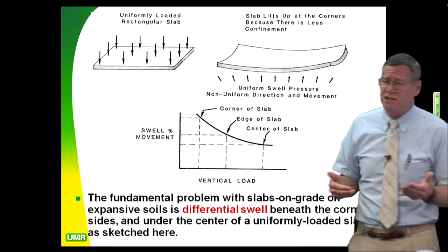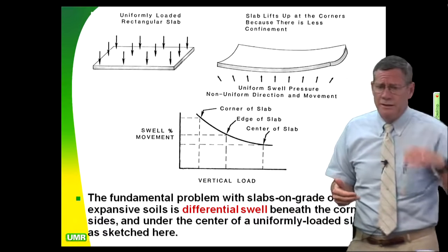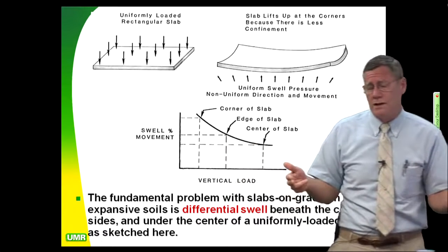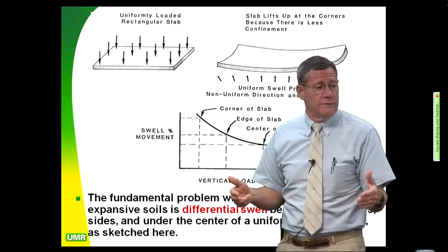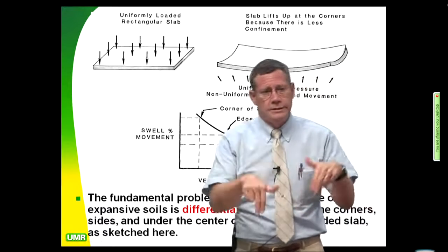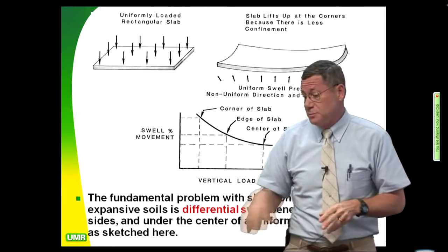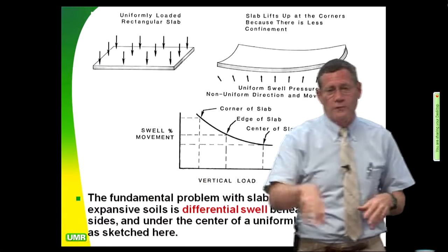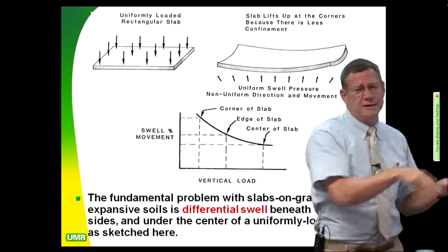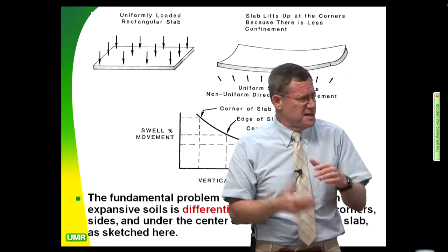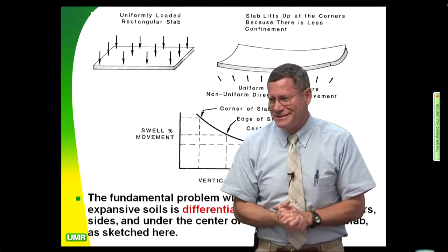And it was actually a guy named Bob McNeil who did a thesis on that back in the 50s with Woodward Clyde in Danville, California, that came up with a concept of the drilled pier and grade beam system. And what he did is he put in 2-footers and 4-footers, 6, 8, and 10, and then for that particular year, 1956 to 57, 6 seemed like it worked.